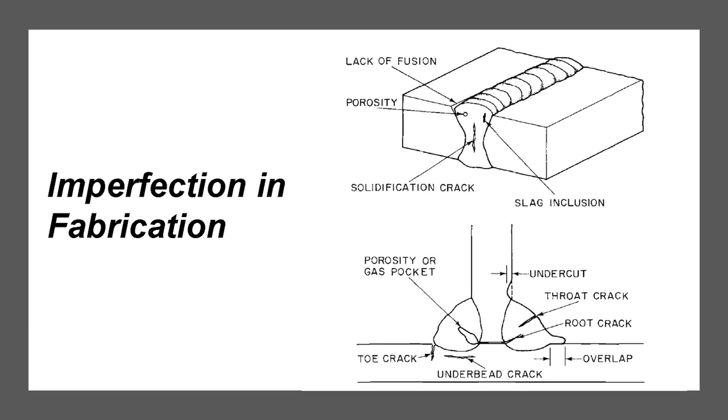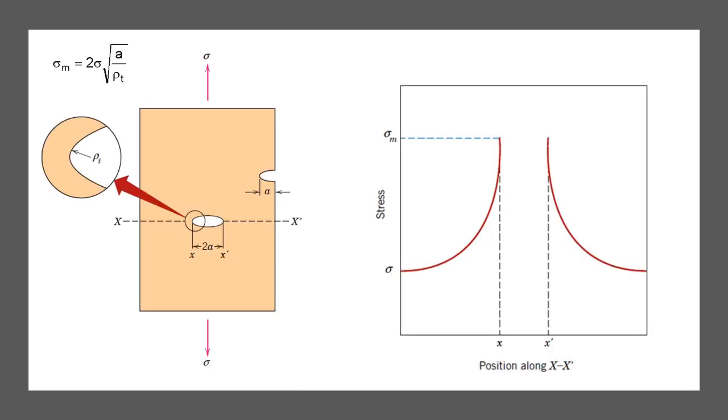It is very difficult to fabricate large welded structures without introducing some type of imperfection in the form of notch, flaw, or discontinuity. The types of flaws that can occur in a steel welded detail are partial penetration and lack of fusion, porosity and inclusions, and undercut or microflaws at the weld toe. Now is the time to discuss the fracture mechanics methodology.